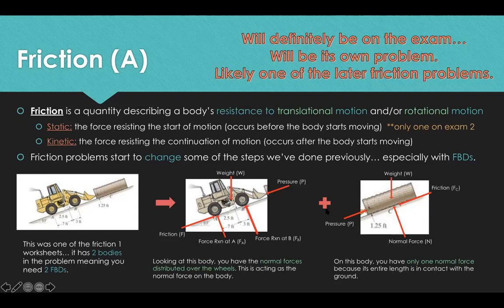So what's nice about this problem is that it again covers everything. So pretty much get familiar with breaking it up like this, because if they give you a friction problem, it'll probably cover a little bit of everything they want you to know. So here you have the reaction forces. For every free body diagram, you're going to have a weight of the body, the force that's keeping the body from falling through the ground, the applied force that you're trying to do, and the friction that's opposing that, right? So I guess a better one to start with is this, right?